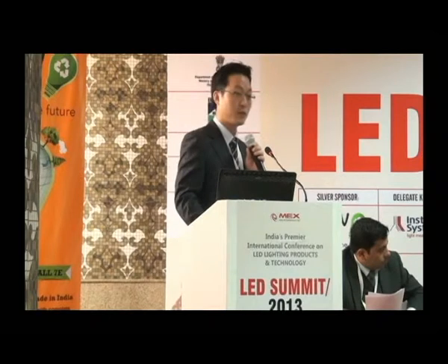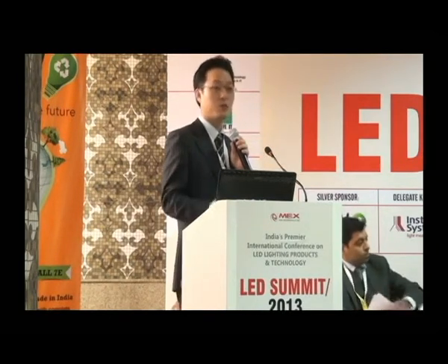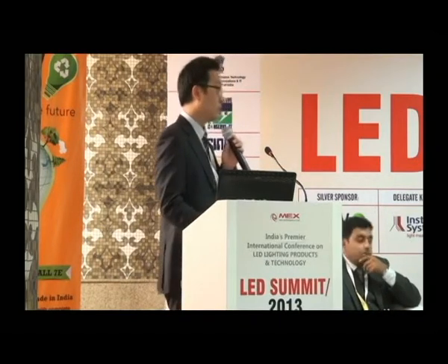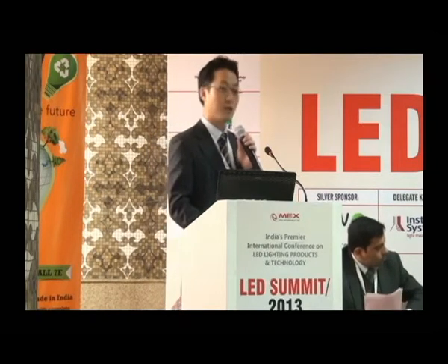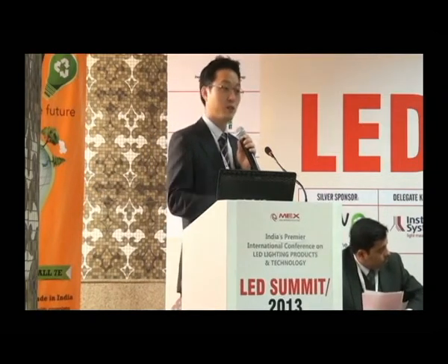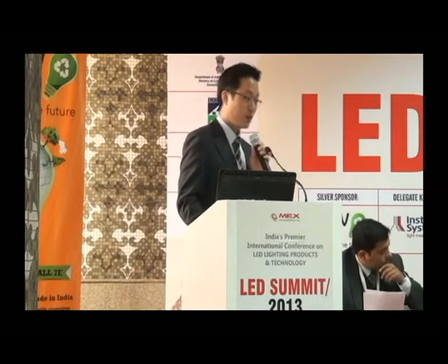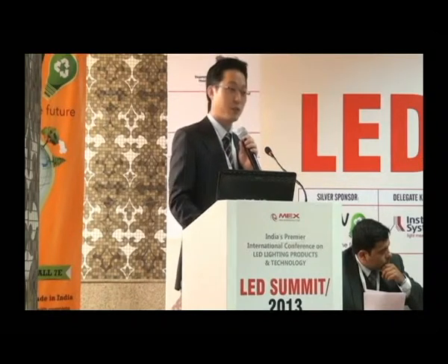As time goes on, the epoxy material changes its color from transparent to yellow. Also, nowadays LED light is mainly used in electronics and installed on a PCB circuit board. In that case, the LED has to tolerate the SMT process.